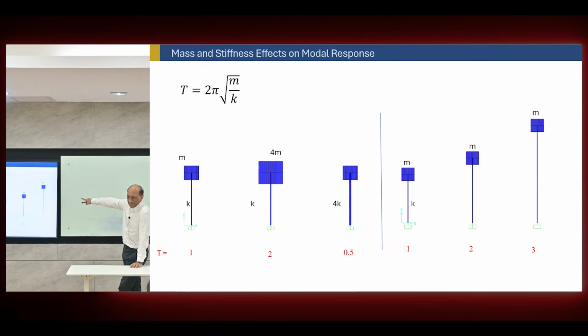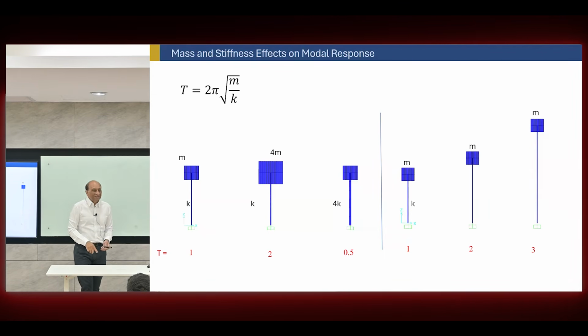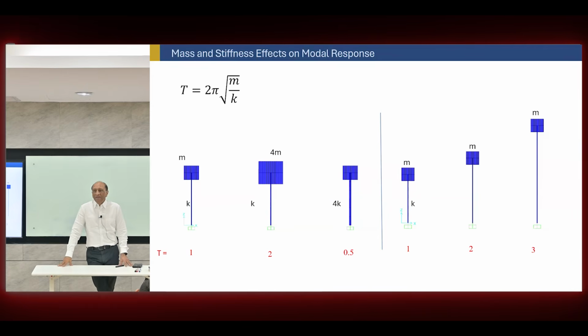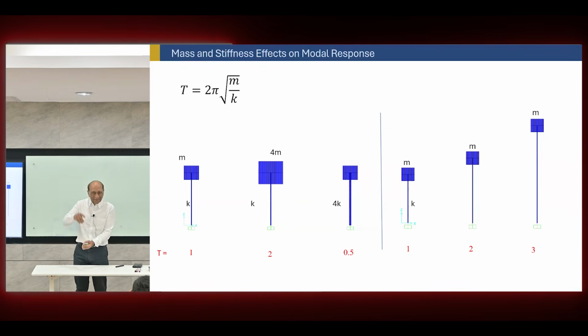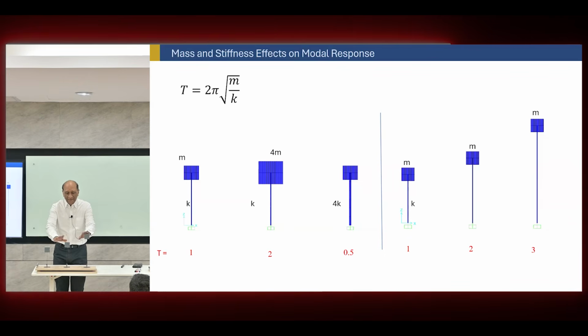The section is the same, but the stiffness will reduce now, because stiffness is not only section size, it's also the height. So we can correlate the mass and stiffness of the member and the height of the member together. Stiffness means the section stiffness, and length is another part of the stiffness, K = EI over L. Okay, so now we have the same mass in all of them.